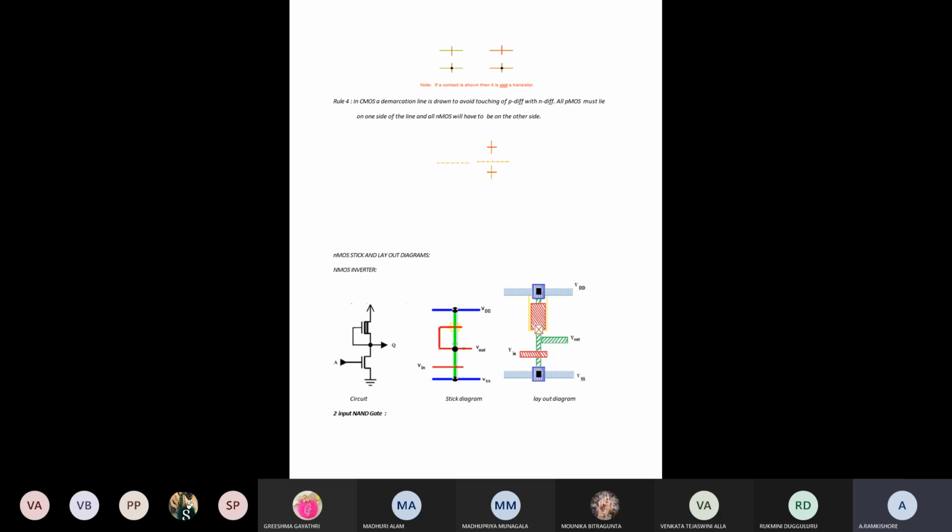After that, we have an output, so we have to connect the output. That output will be connected at the depletion mode transistor side. So we extend that output with the same polysilicon material for the V out, clear.